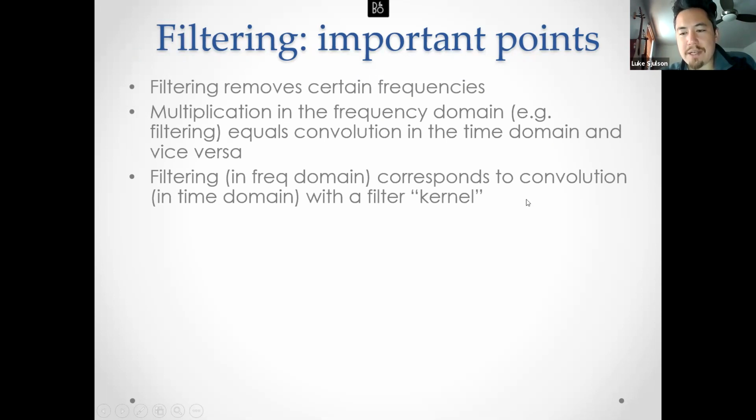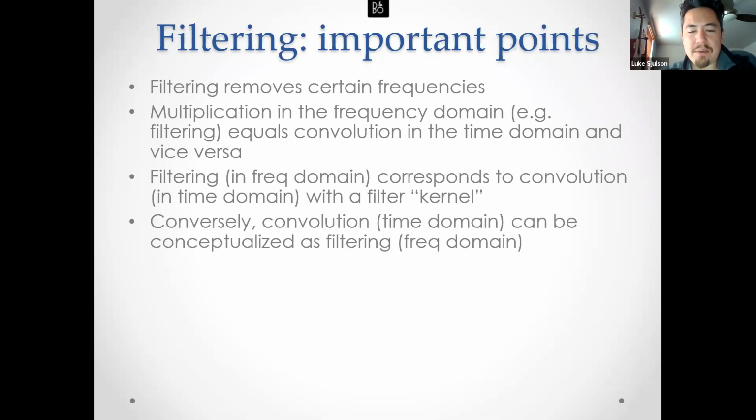So we often talk about the convolution kernel, which can be a Gaussian, for example, convolution with a Gaussian. Interestingly, the Fourier transform of a Gaussian is also a Gaussian. So if you convolve with a Gaussian for your hot air balloon image, it's actually the same as taking the Fourier transform of that and then multiplying it times a Gaussian transfer function. Anyway, I don't want to get too much into that unless we have spare time later.